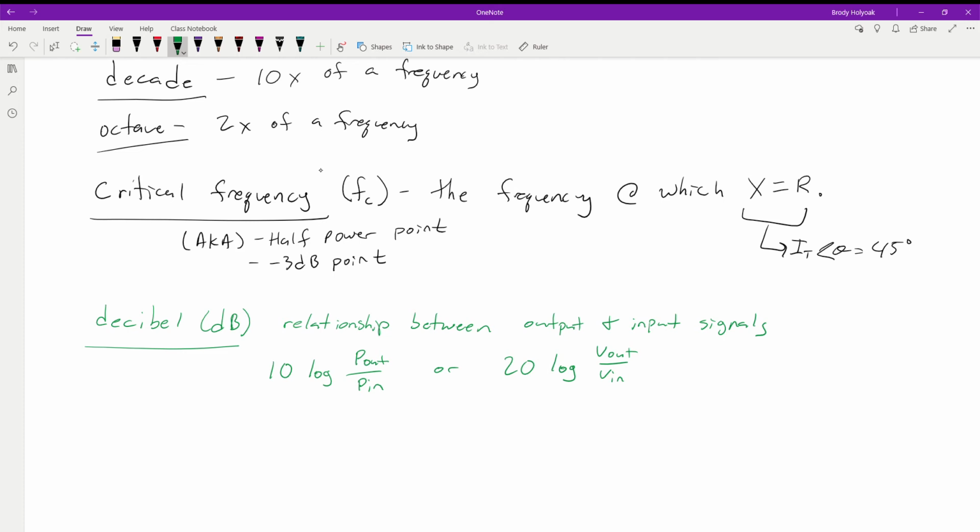So like before, when it says we have a negative 3 dB point, what this means is we've gone down, we're losing 3 decibels of our output compared to our input. This also represents 0.707 of our volts peak. So this is where this all comes along. This is why this is the negative 3 dB point, because if you take your RMS values, things like that, you can solve through these. This 0.707 is going to show up all over the place.